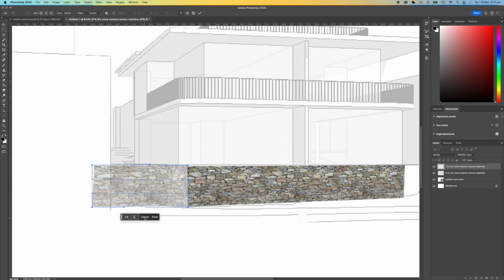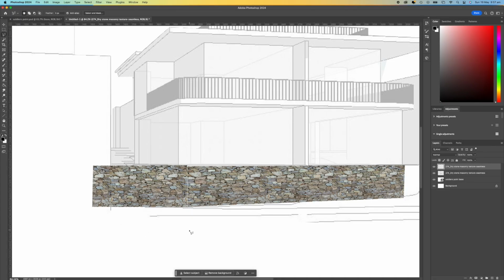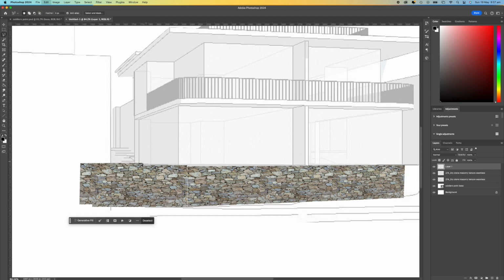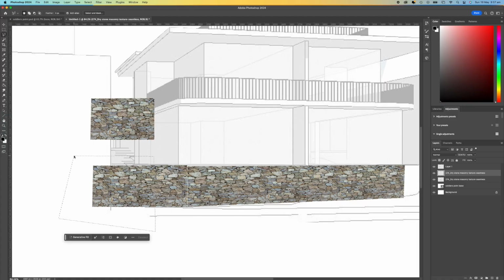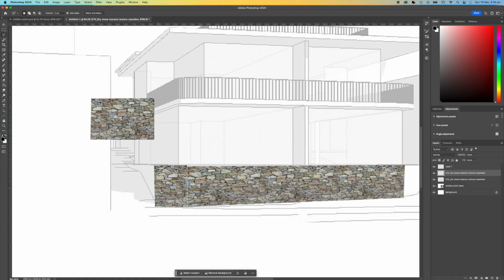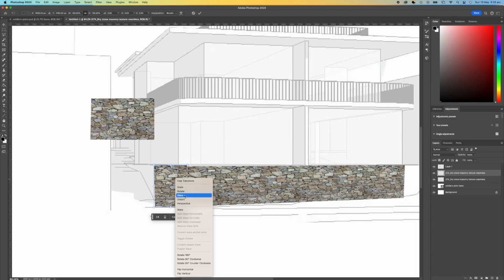This is actually a bit big because we just want to be able to corner the very corner and curve it with more of the warp tool. So I'm going to select this and duplicate it so we've got another extra portion of this wall to use later. I'm going to press L for lasso and then cut off the extra part that I don't need.